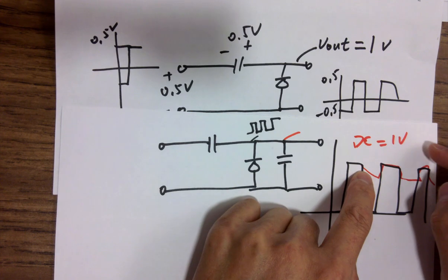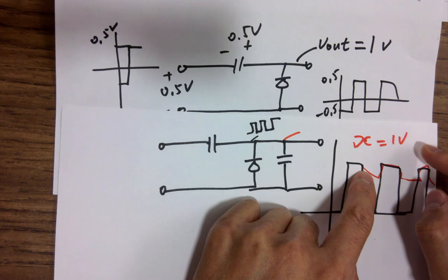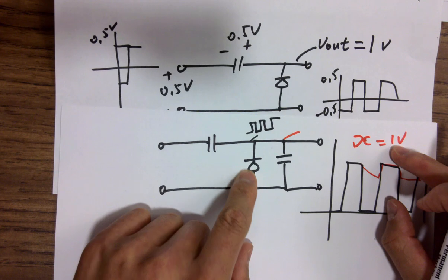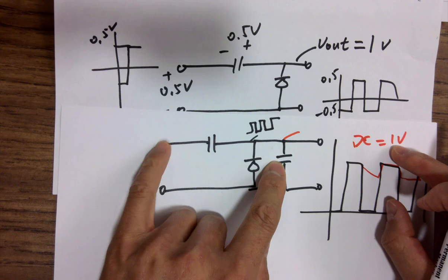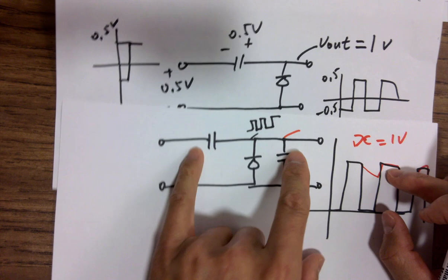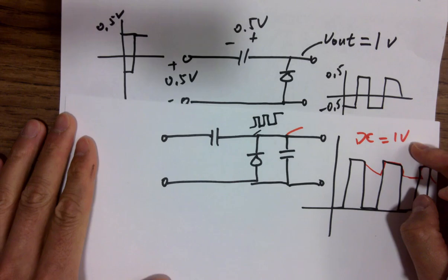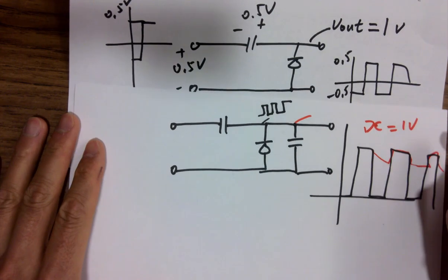Mm-hmm. That's a lot of. It's a commercial circuit actually. So a lot of high voltage generators are using voltage multipliers. They just pick up the correct diodes and capacitors, adding like 10 stages, and eventually can boost it to like 2,000 volts or something. Okay, that's how that works. But it's a digital circuit, so we are not dealing with that.